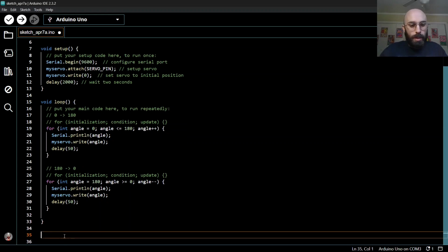What I'm going to do is come down here and write a function, and in order to be able to call a function, we have to come up with a unique name, or identifier, for it. We're just going to call this servoMove, let's say, and this is our name for it. Then in front of the name, we need to put the type of the value it's going to return. In front of setup and loop, you can see there's the word void, and that means that these functions don't return any sort of value.